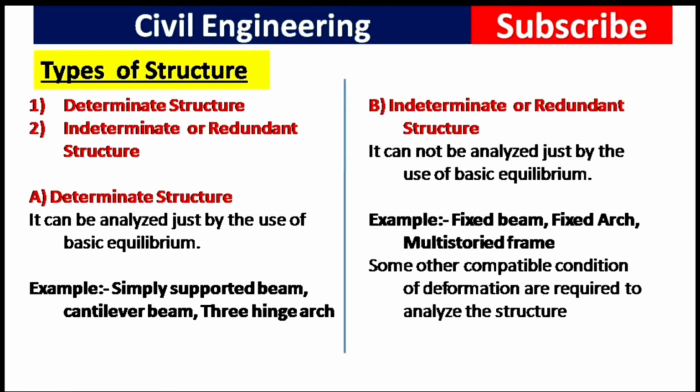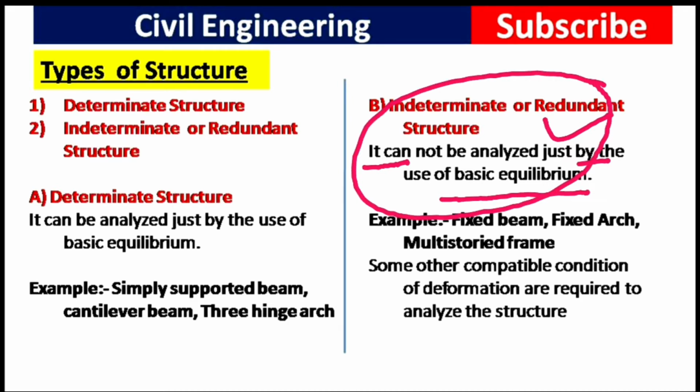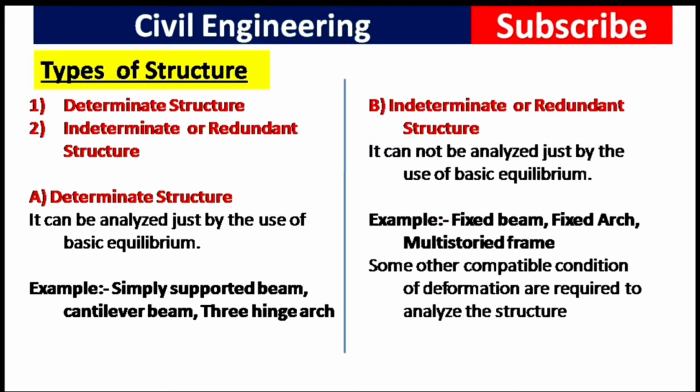Now the other structure is indeterminate or redundant structure, and it cannot be analyzed just by basic equilibrium. Guys, these types of structure cannot be analyzed the same as determinate structure. Okay, and examples are fixed beam, fixed arch, multi-storey frame, etc. Let us see in the picture.